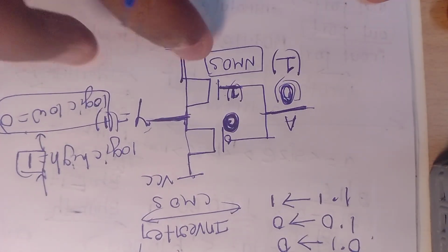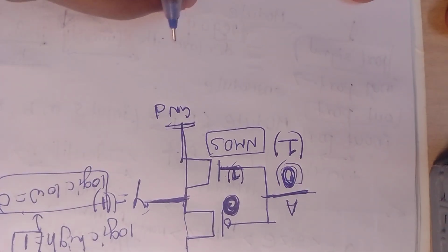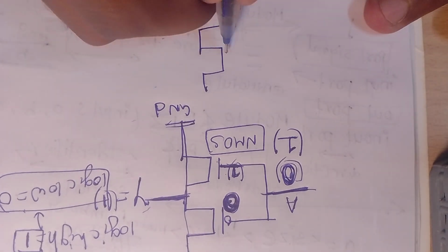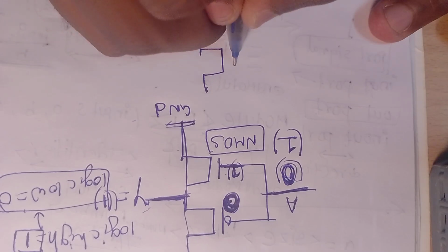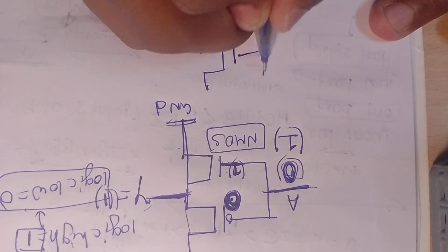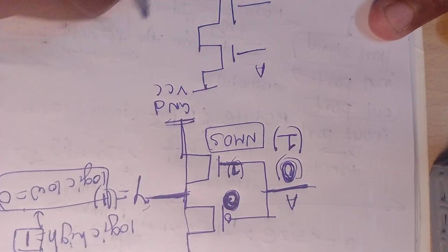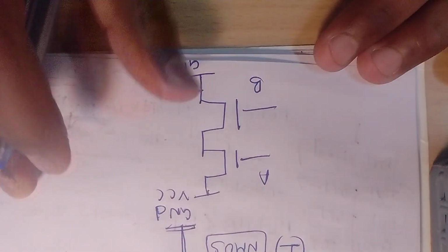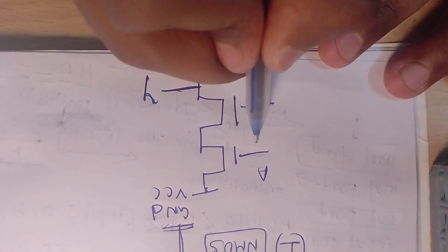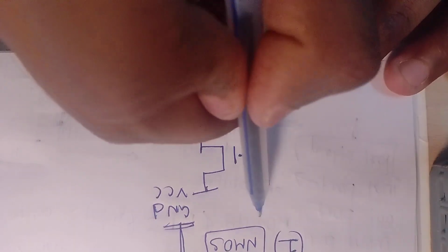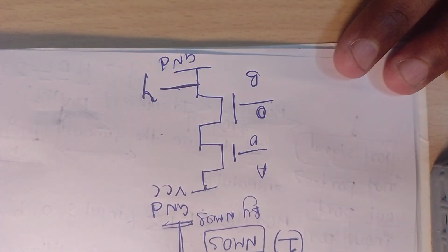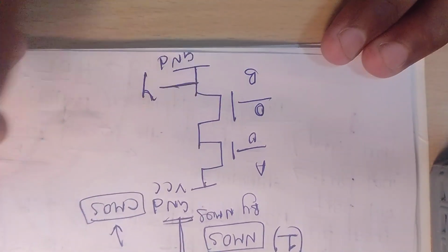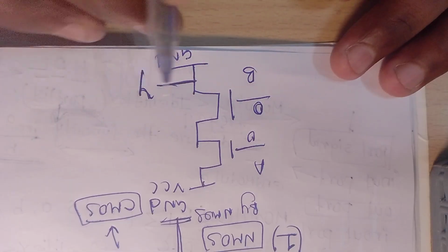In the same way, the AND gate will also be designed. How will we be able to design this AND gate? We can use NMOS. We will take the output from here. Whenever you apply 0 0, what is going to happen? I have designed it using NMOS only. You can use PMOS, and you can also use CMOS architecture. In CMOS architecture we have to use both NMOS and PMOS, but now I have used NMOS only over here.